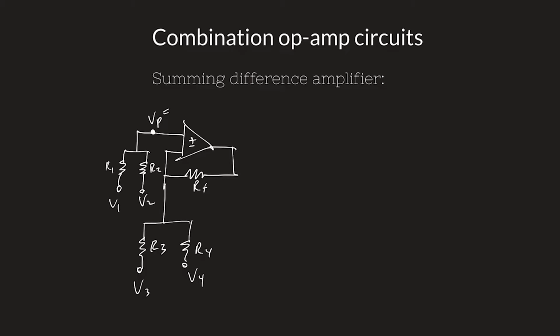So VP. It's a linear circuit, linear in the inputs, so I can give it a VP due to 1 plus VP due to 2. And there's also VP due to 3 and VP due to 4, but those are 0, because whenever only 3 is on, this VP node is grounded, and when only V4 is on, the same thing.